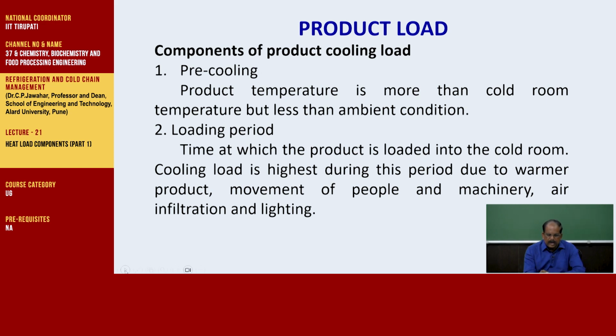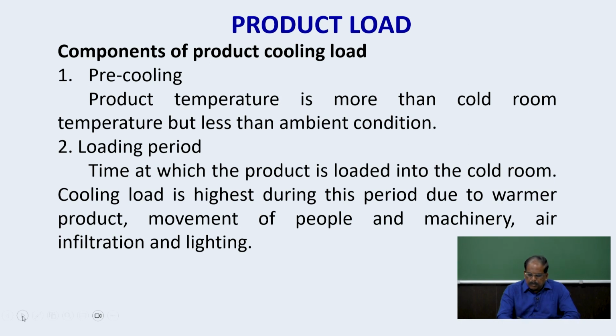Next one is the loading period, the time at which the product is loaded into the cold room. Cooling load is highest during this period due to warmer product, movement of people and machinery, air infiltration and lighting. So the cooling load is highest during this loading period. This is due to the movement of the people, movement of the products or the goods entering into the cold room.